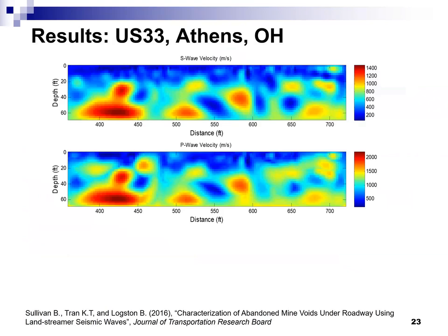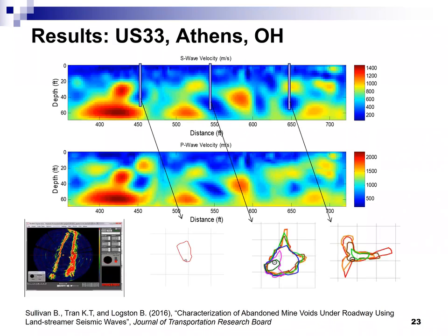So we recommended 3 locations, one here and one here, because this one we don't see in the P wave, so we did not recommend that they drill it. You don't see it from the P wave velocity. Water, is that? Yeah, we think that is very deep water, so it's not there, so it's still high. So we don't think, if it's like this, it may be an air-filled void, right? And this one needs to go to 300. Right. And if it had a Poisson's ratio, it would be nothing like 0.49.